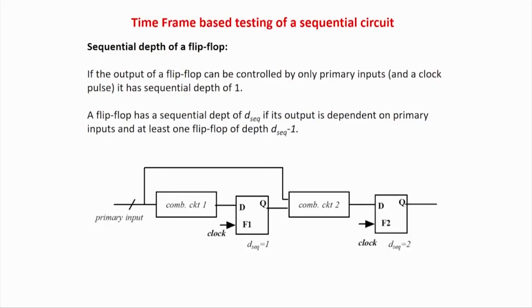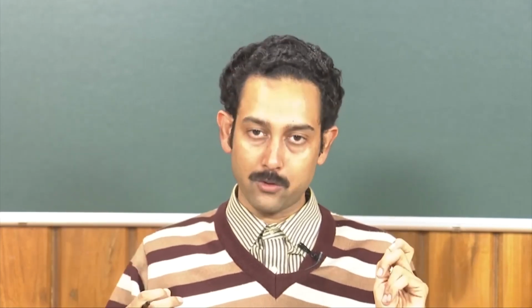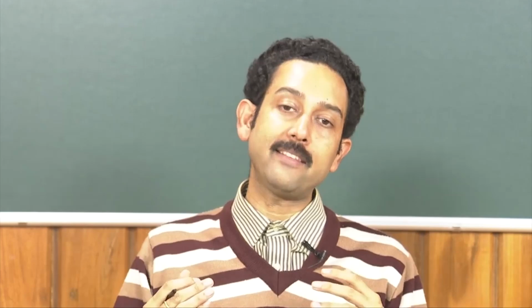As we go through these lectures, you will automatically be motivated and find out why scan chain optimization is so important, because a scan chain is not only about the flip flops you put in additionally, but also about the pinouts. One extra scan chain you put in means one additional pinout has to be there. Therefore optimization of the scan chain has a greater role to play compared to other cases like compaction and decompression circuits, etc.